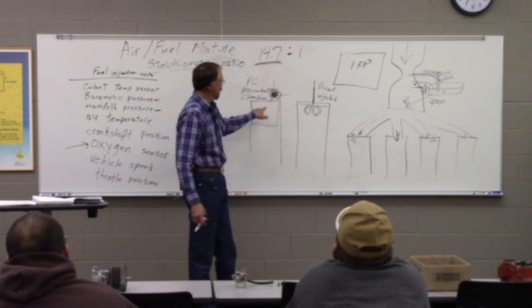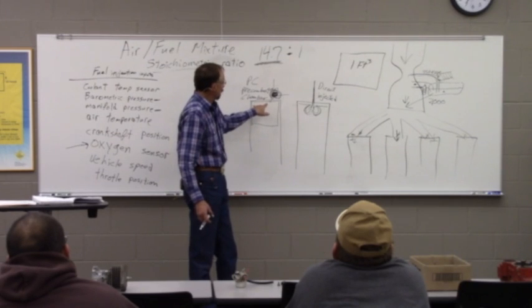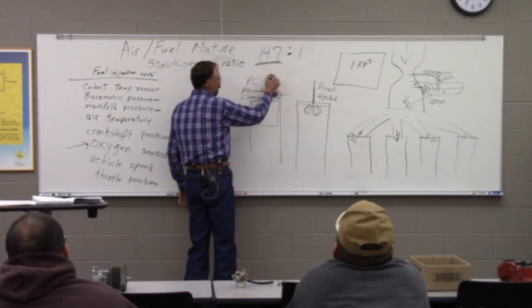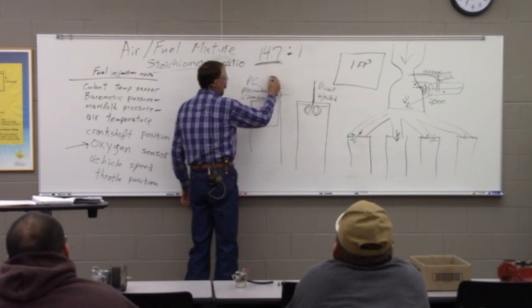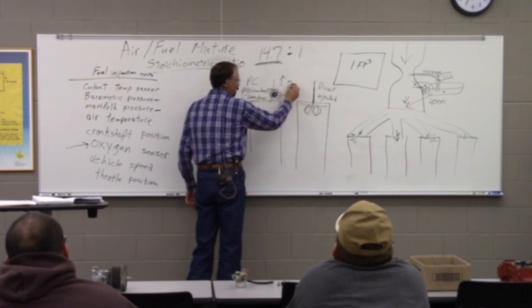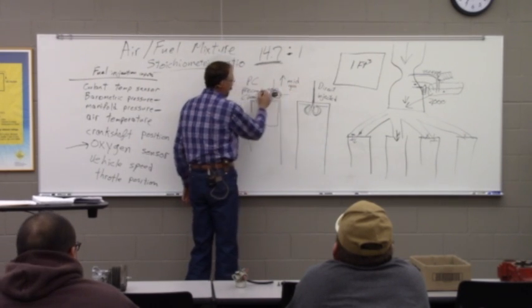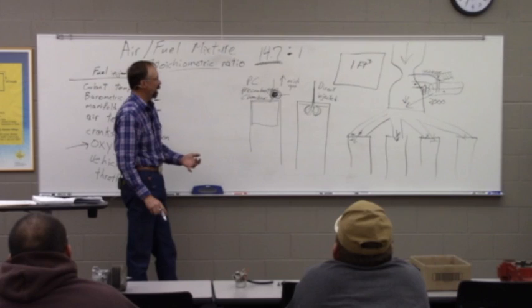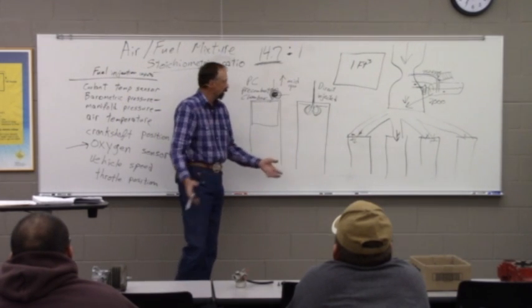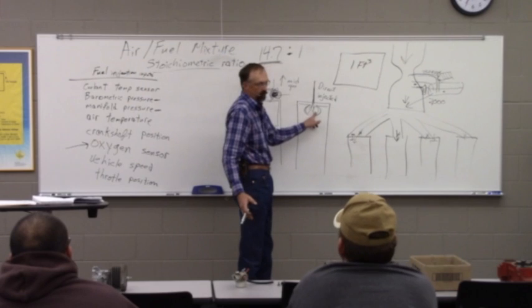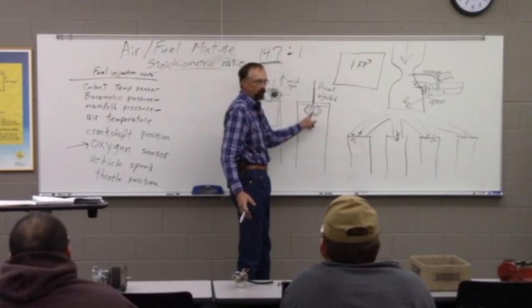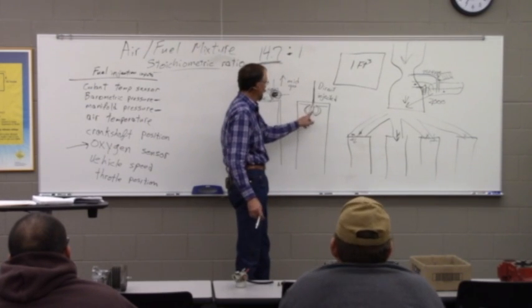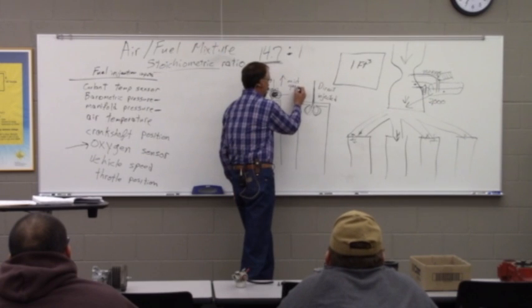So interestingly enough, a lot of the engines that you may have, for example, all the Ford diesel engines up through mid-year 94 were pre-combustion chamber engines. All the old 6.9s and 7.3s that were not Power Strokes. Whenever Ford went to this direct injection system is when they started using the name Power Stroke. And that happened actually mid-year 1994.